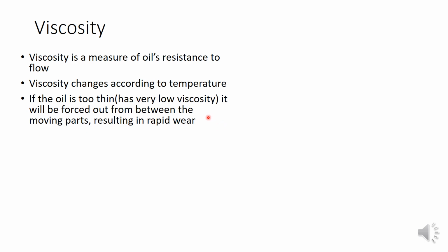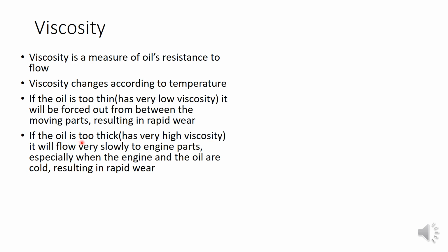This also has some problem. If you are using an oil that is too thick, with very high viscosity, it will flow only very slowly. We know that the resistance will be more, so it will flow only very slowly. So it takes more time to reach the engine parts, so it also will help in wear. So that is the important thing. If the viscosity is very low, it will increase the wear, and if the viscosity is too high also, it will result in wear. So we have to select an optimum viscosity for our oil in a particular engine.